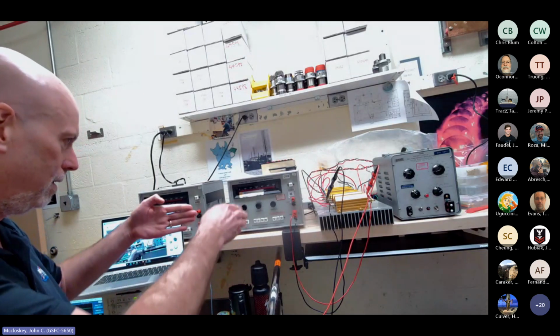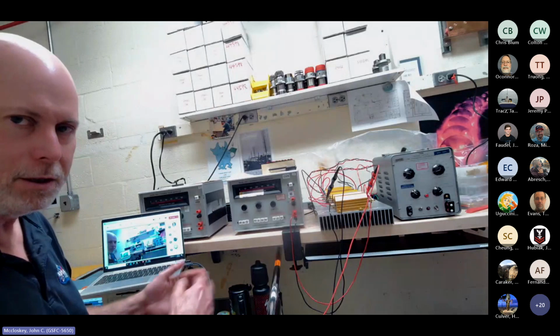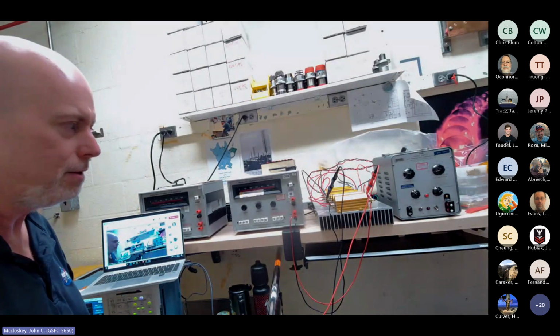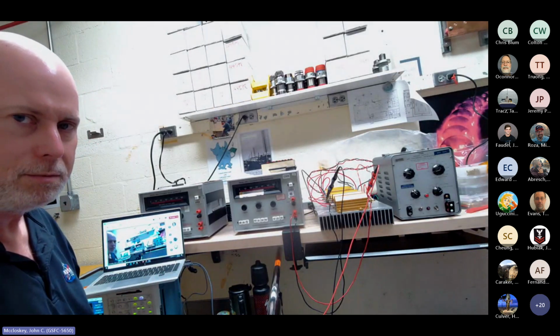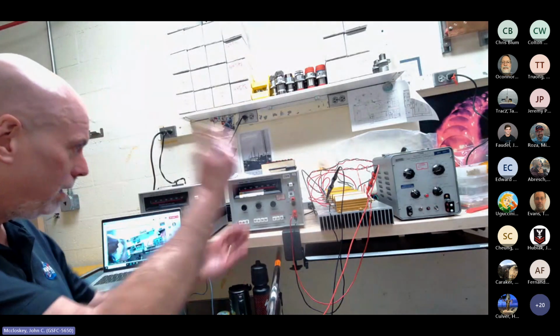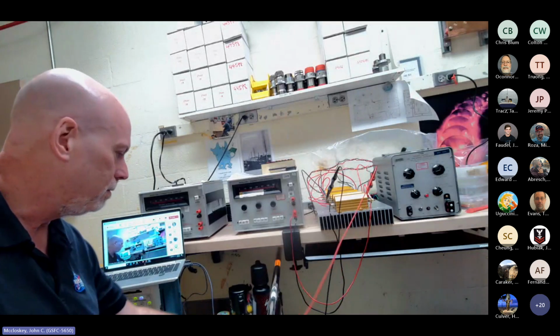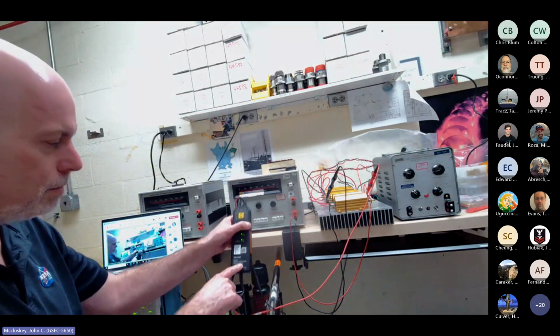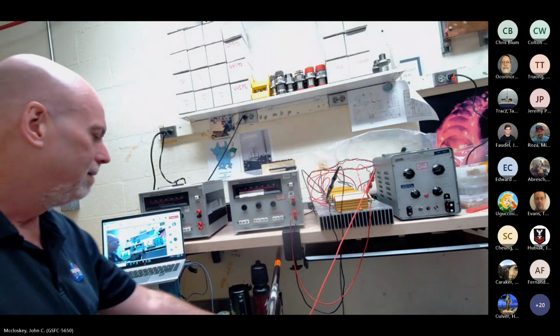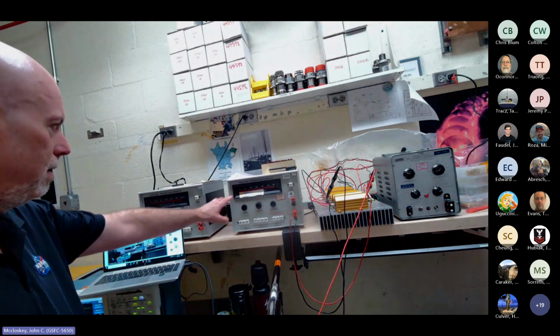You don't want your reference connection going through your scope into facility ground and all that stuff. You don't want that to perturb your configuration, right? Which it can. So we got a differential, and we're dealing with high voltages here, so this is specifically a high voltage differential probe. So there we go. I'm going to go ahead and turn this on.